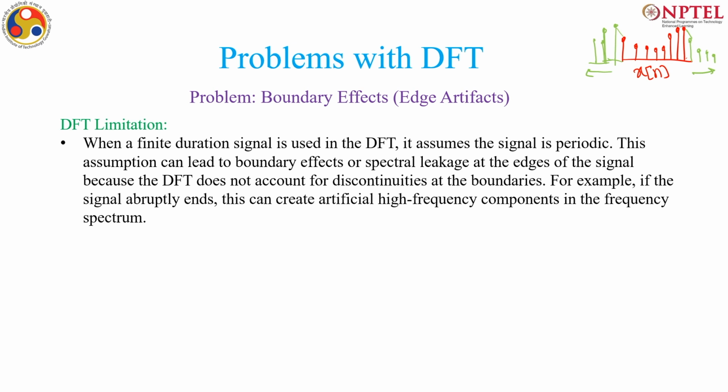present. This will be probably clear if, say, this sample had a smaller value, then you can acknowledge the boundary effect nicely. Say this value is small. So, now you see this sudden change is creating an artificial high frequency which is not at all there in the signal, or if this value is negative. Same thing will happen if I change this value, because it is a periodic extension. So, if this value is very small like this, this is an artificially induced high frequency component.